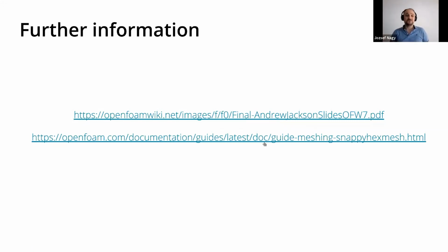And also now there is a very good official documentation of snappyHexMesh, so you can also click that link in order to learn more about snappyHexMesh. I just showed you the basics, the 5 most important settings in snappyHexMesh, plus surface feature extract and plus block mesh. But if you want to know more, just here are the references in my slides.